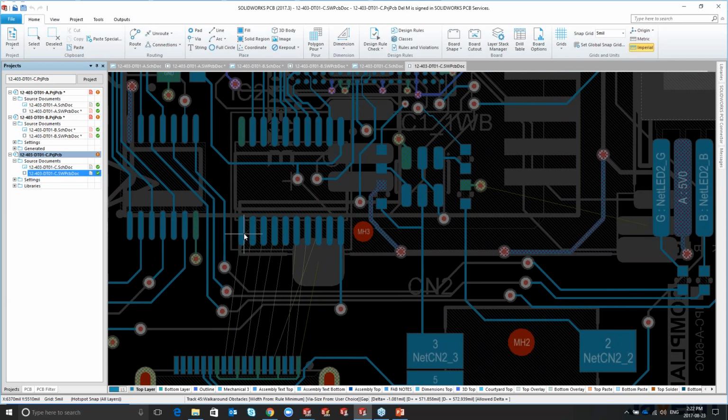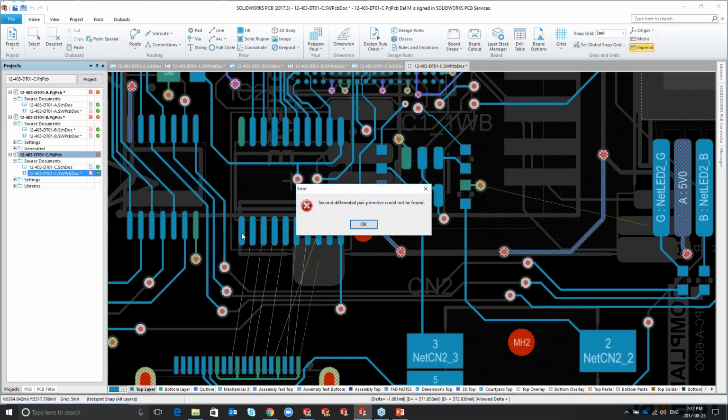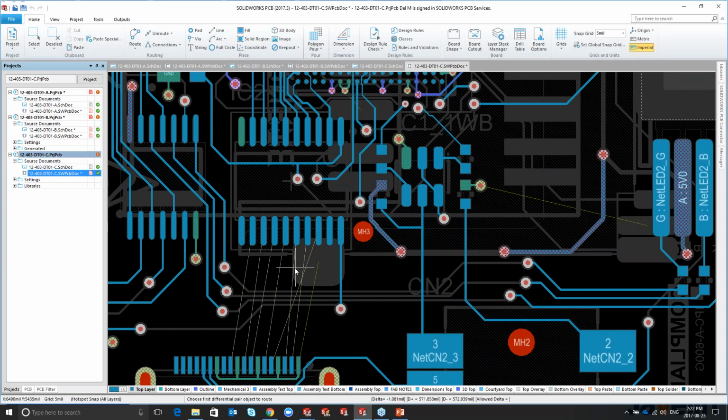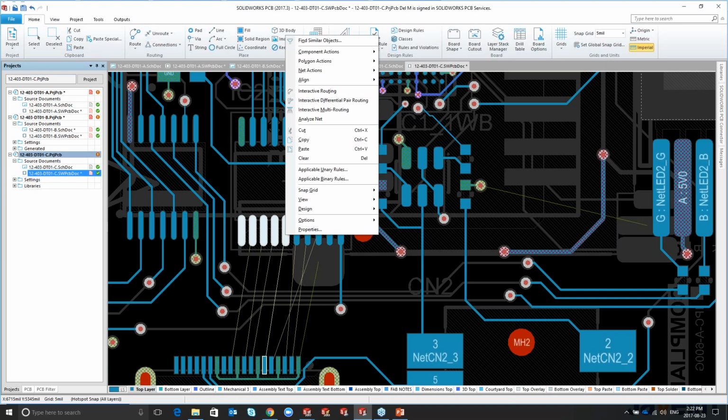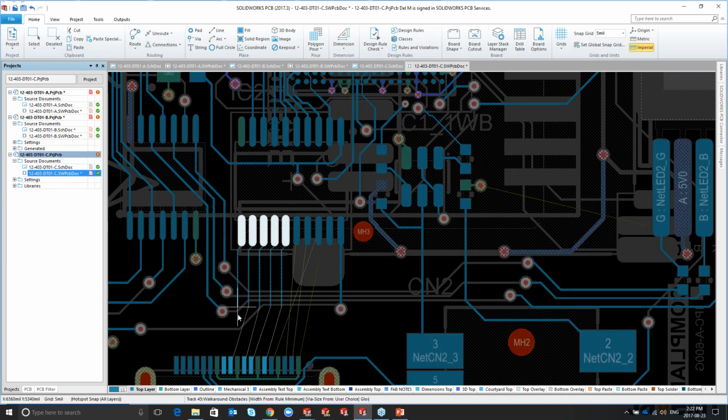And we can go a little bit closer, and we can start. We can then go ahead and pick these components or these pins on the component, and I'm holding the shift key over here to group select it, and at this point they can simply right click on it and say interactive multi-routing. With that, a few of them will go in there, and you also have shortcuts to go ahead and begin. You can increase the thickness or the width of those particular routes.